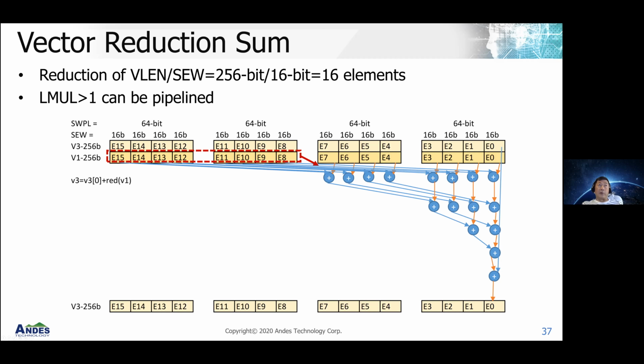For the integer operation, it's a single cycle operation, so the latency of the vector sum reduction for integer will be 5 clock cycles. For floating point, each floating point add is 3 cycles, so we take 15 clock cycles latency for the reduction of floating point data.